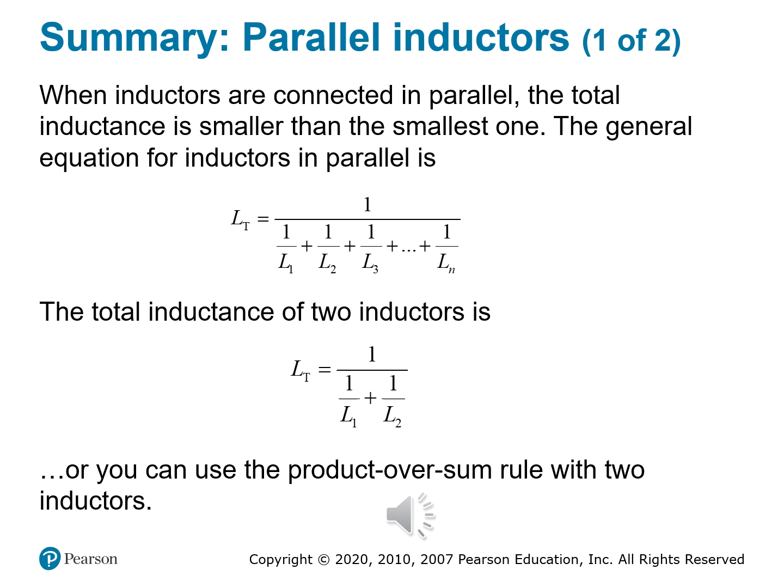So why does inductance drop in parallel? Because each coil provides an alternate path for current to build a magnetic field. So more paths, less overall resistance to change. The magnetic energy is now distributed between multiple coils, and the net effect is a lower overall inductance. The practical reasons to use parallel inductors are maybe you want to reduce overall inductance, to share current load across components, and maybe to fine tune circuit responses, especially in RF or tuned filters. So just remember this, if you're combining inductors that are close together, mutual inductance can influence the total. So always take spacing and coupling into account in your design.